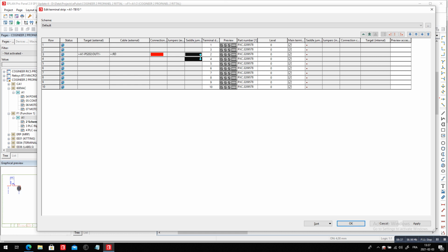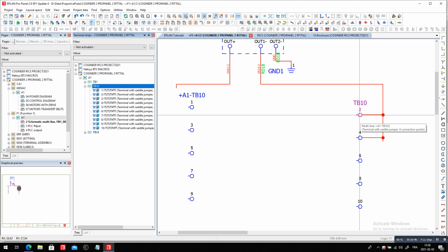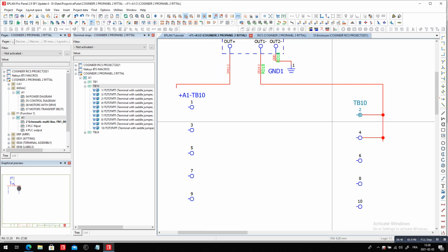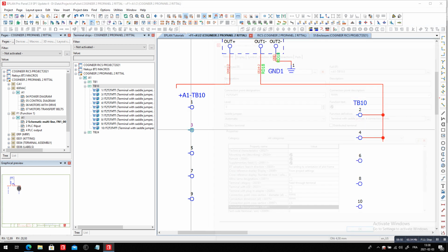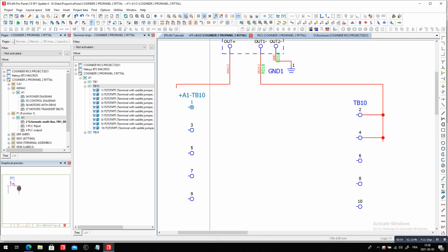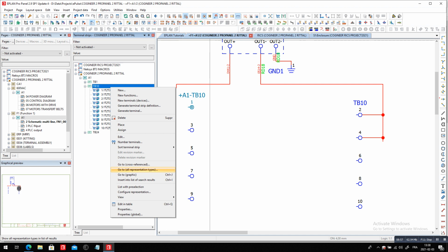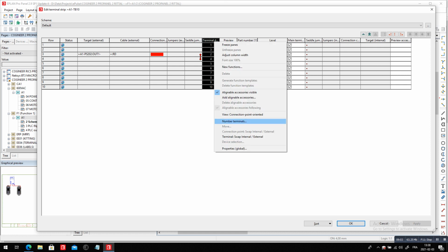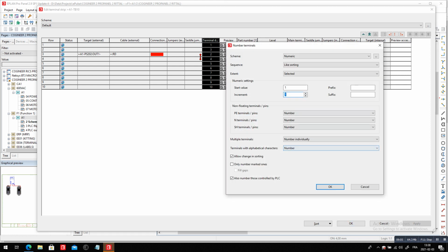Of course, now if I click OK and I look at number 2, its device position will be device position number 3. The number 3 here actually moved into position number 2. So technically, if you want a perfect match between what you see in terms of sorting and numbering, it's always a good thing to just go here, right mouse click, number, and you select again the sorting. So now it's all nice and dandy.